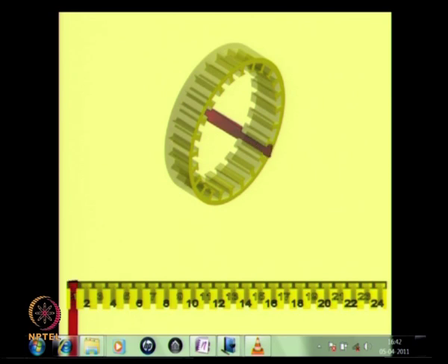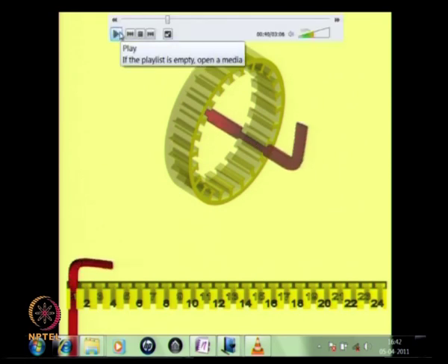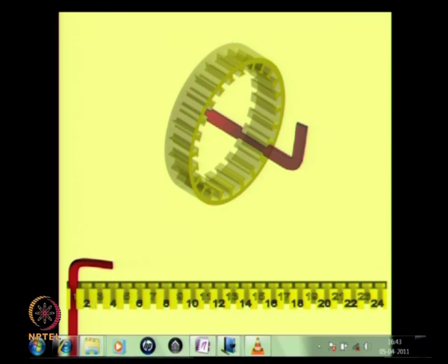Now, here you see the stator being wound. The stator slots are shown here also for ease of understanding, because normally in books it is this that can be easily represented. The stator slots are also numbered here, and we have seen that the stator has 4 poles, and this machine, the system that we have here, has number of slots equal to 24.